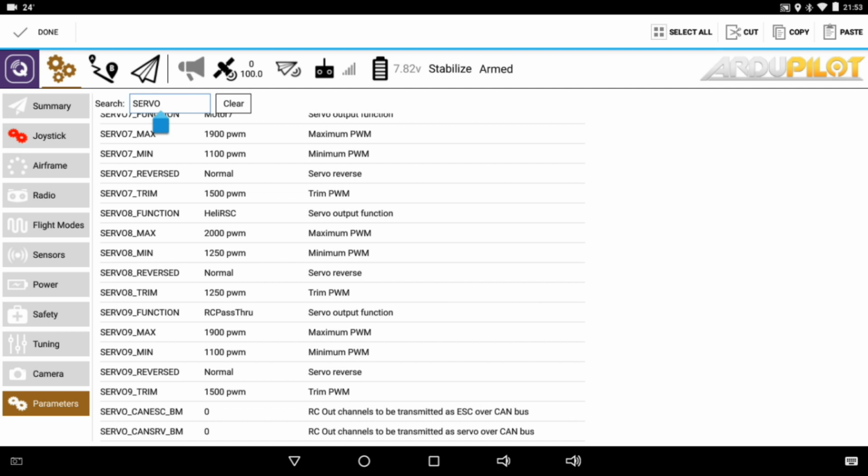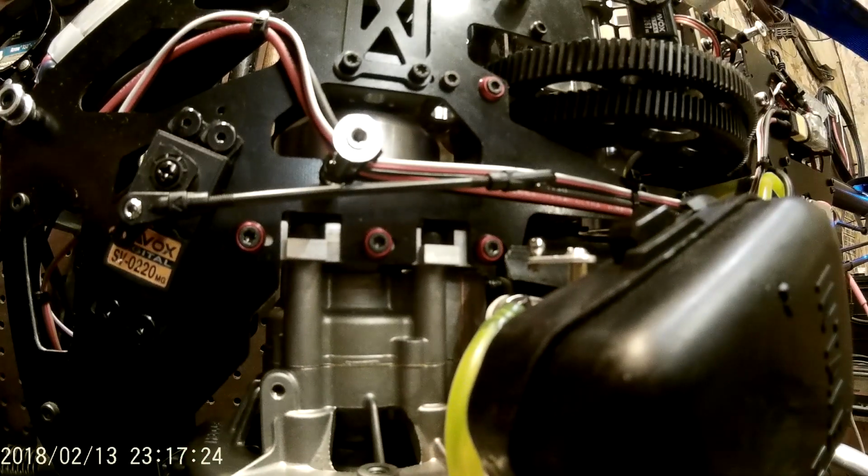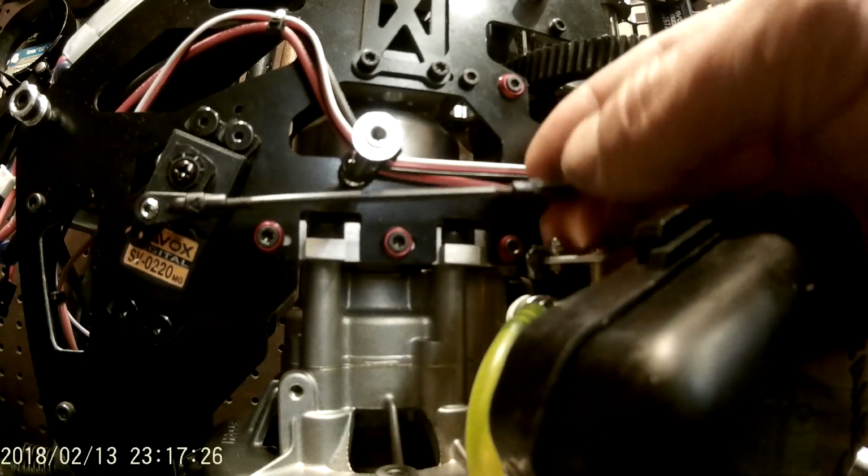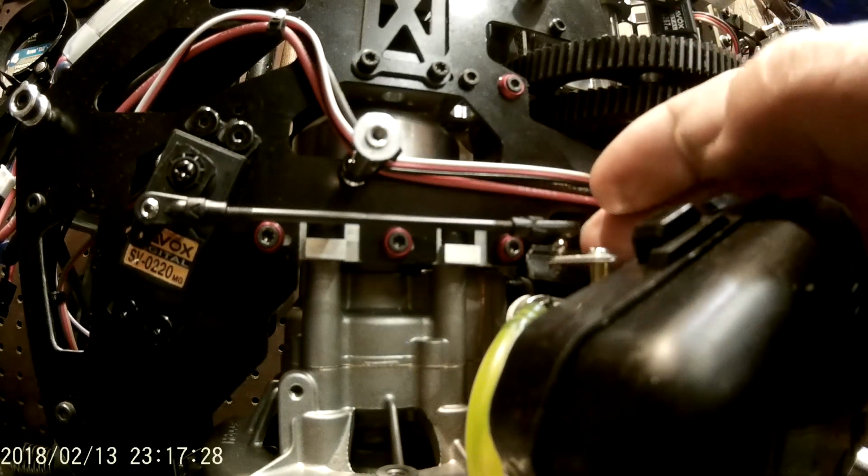And we're going to throw the throttle interlock switch. We're going to release the throttle interlock. My radio has a timer in it. You heard the timer beep. That signifies the end of the run-up that is set in ArduPilot.